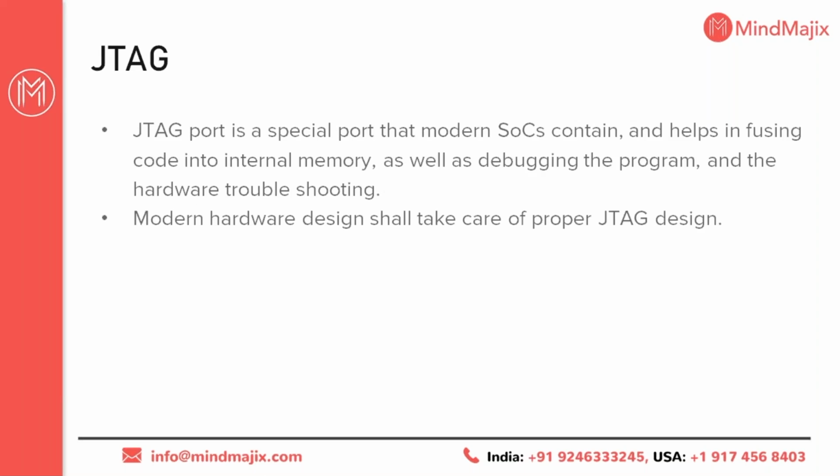JTAG design. The JTAG port is a special port that modern SoCs contain and that helps in loading code into internal memory, as well as debugging the program and troubleshooting the hardware. So modern hardware design shall take care of proper JTAG design, which involves connecting the microcontroller's JTAG to the proper pins of the in-circuit emulator. Any in-circuit emulator is typically connected to the JTAG port, and through the in-circuit emulator, one would download the program and all that. So this JTAG design is an important aspect of the microcontroller design.